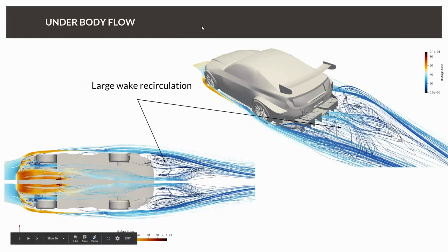The next thing, to further visualize this, we created some streamlines, and now you can really see how things are working. The air coming to the front of the car is split by the splitter, so a part of the flow is guided around the front of the car, streaming around the car and touching the rear tires, and that's where we have this high wall shear stress.